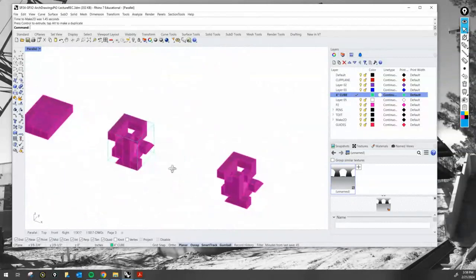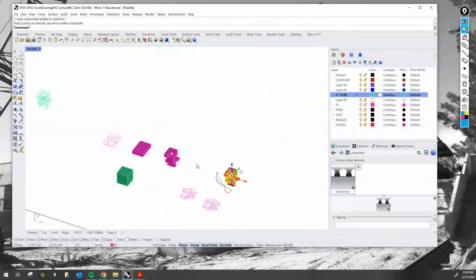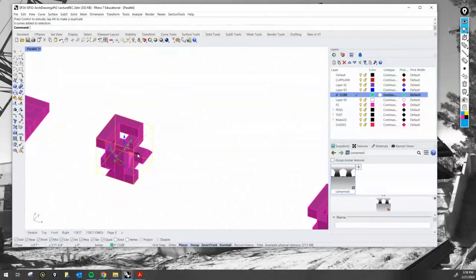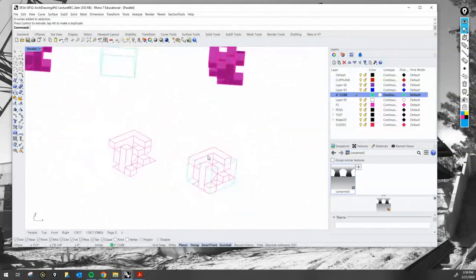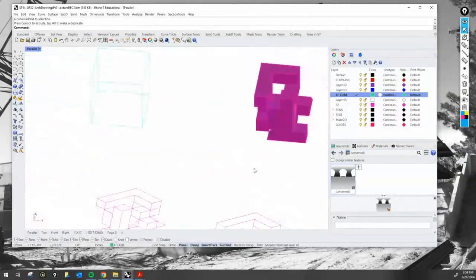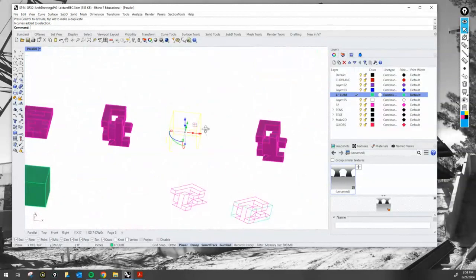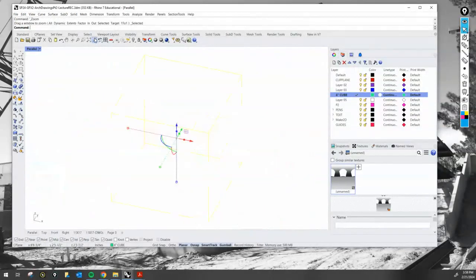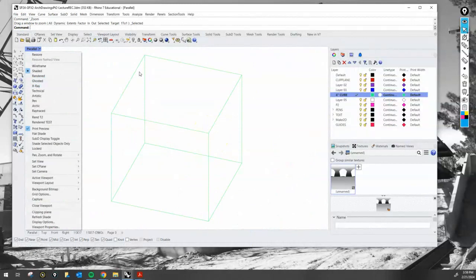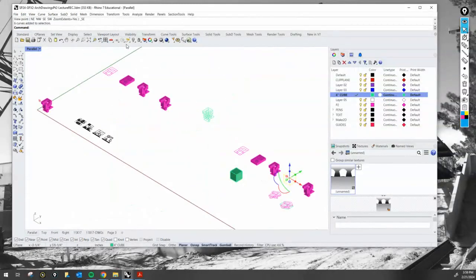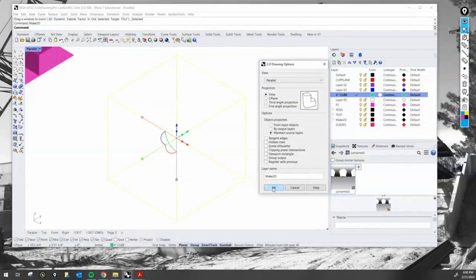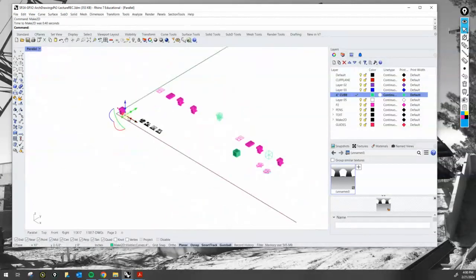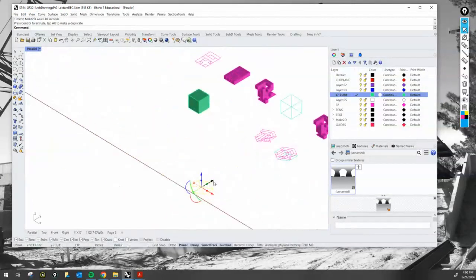Okay, and then lastly, let's do one more exercise right here. What happens if we do them separately, right? Because I actually want us to see what the graphical difference of being overlapped versus individual is. And what I mean by that is select the cube, just the wireframe, zoom select. Well, actually, we should have set the view, southeast, select the cube, zoom selected, type make 2D, enter, click OK, drag your output.